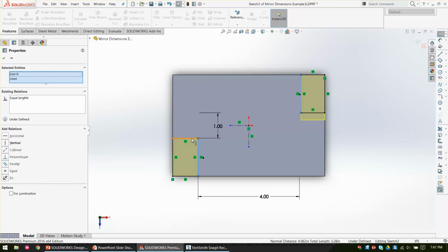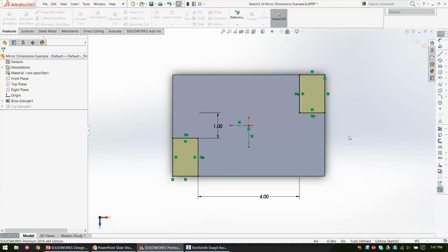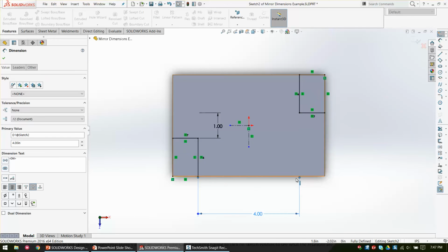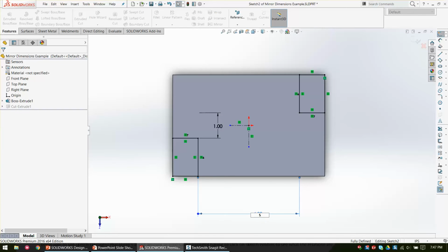So I'll just make these equal again because I want these to be equal. And you can see here I have a dimension that's just hanging off into space, and a lot of people got confused why that's not touching there. That's the example: I can double the dimension off the center line, and then I have complete symmetry here without relying on that symmetrical geometry. If I ever have to delete it and recreate it, which I can do in like 3 clicks and 10 seconds, I don't have that constraint. None of my dimensions disappear.